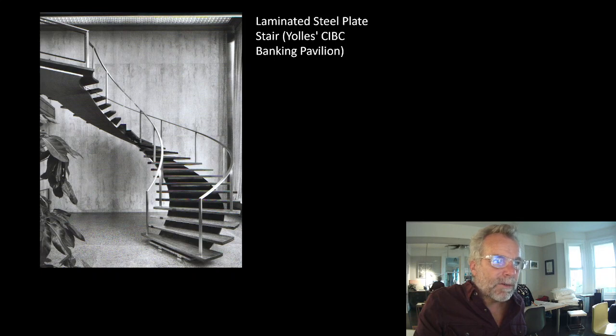It's absolutely extraordinary. And this is where I was saying, here we've got a spiral stair. It doesn't have a central column. And these plates are much, much too shallow to span the length of that stair. What makes this work is that a planar spiral is actually anticlastic, and so it's behaving as a shell. I'm baffled by this stair to this day. It's amazing.